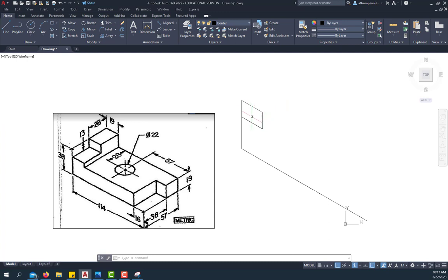So right now I've got this little cutout area that's not even actually part of the object. I still have to go over in the right view to put this 57 depth dimension. Okay, that's going to make me have to click on F5 and change my plane. So I'm going to go back to the line command.